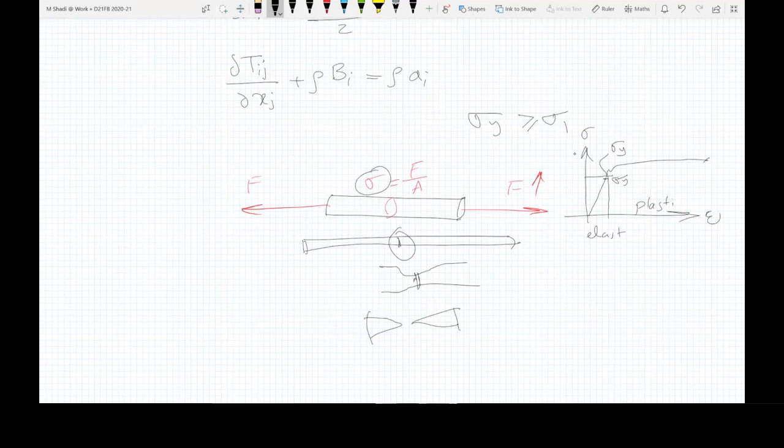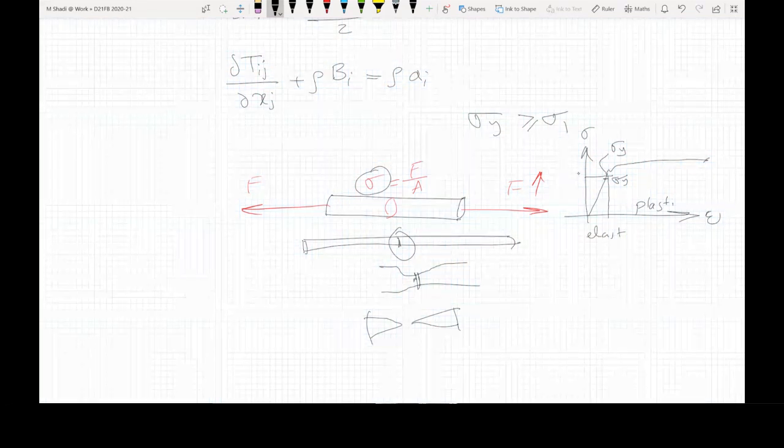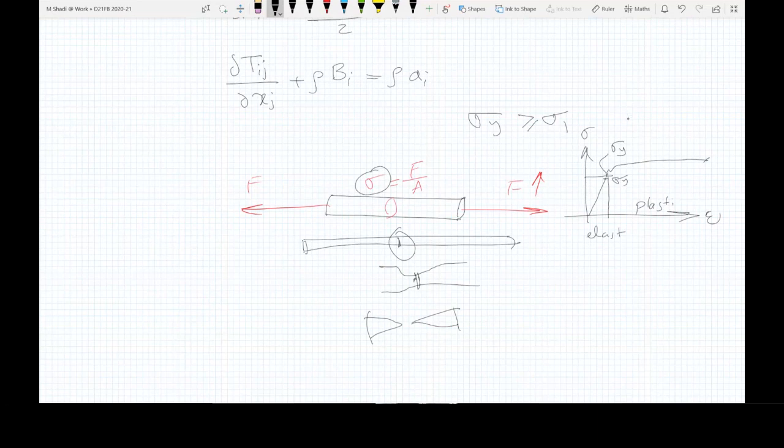I mean, thermal stresses are not a regular type of load that is going to be described quite easily, for example, in the Eurocode. On top of that, you have quite a lot of other forces that are active on this object. And then you have a really complex combination of material behavior and stresses, normal and shear, and you really need to understand how they work together.